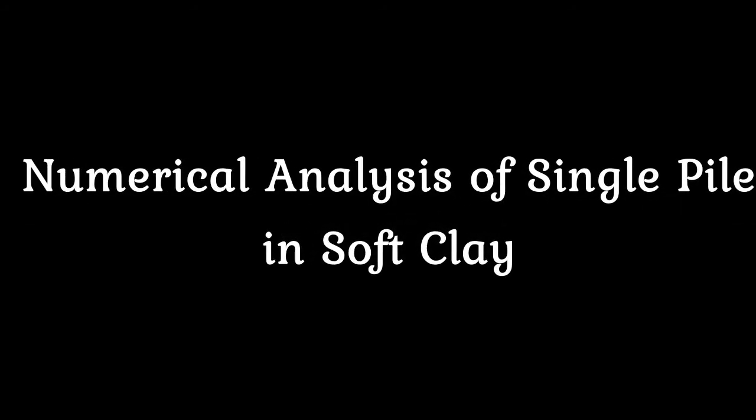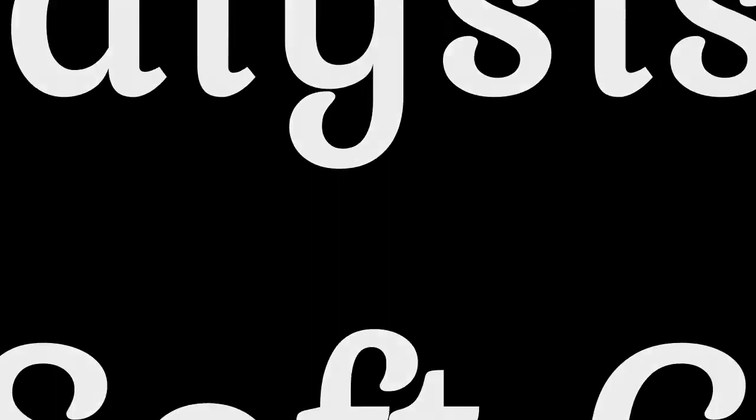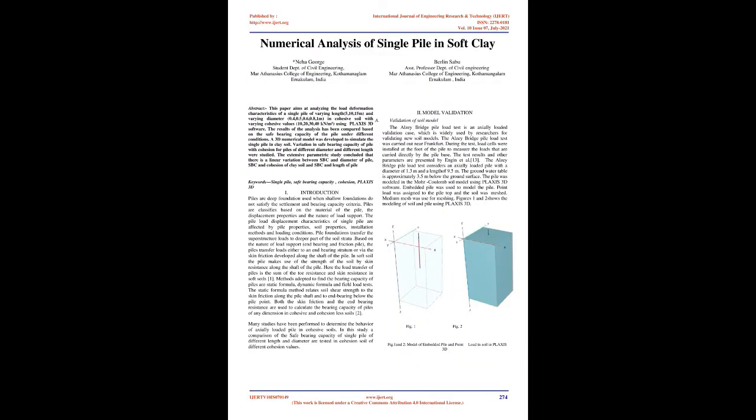Numerical analysis of single pile in soft clay. Abstract: this paper aims at analyzing the load deformation characteristics of a single pile of varying length, 5, 10, 15 m, and varying diameter, 0.4, 0.5, 0.6, 0.8, 1 m, in cohesive soil with varying cohesive values, 10, 20, 30, 40 kN/m², using PLAXIS 3D software.